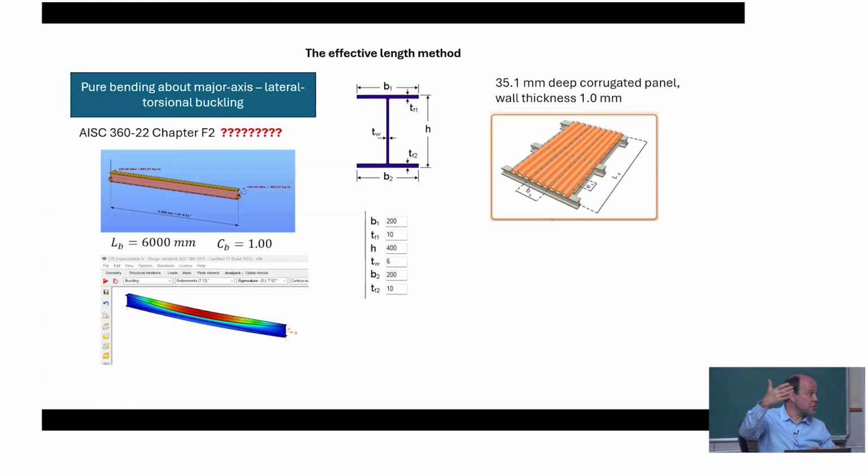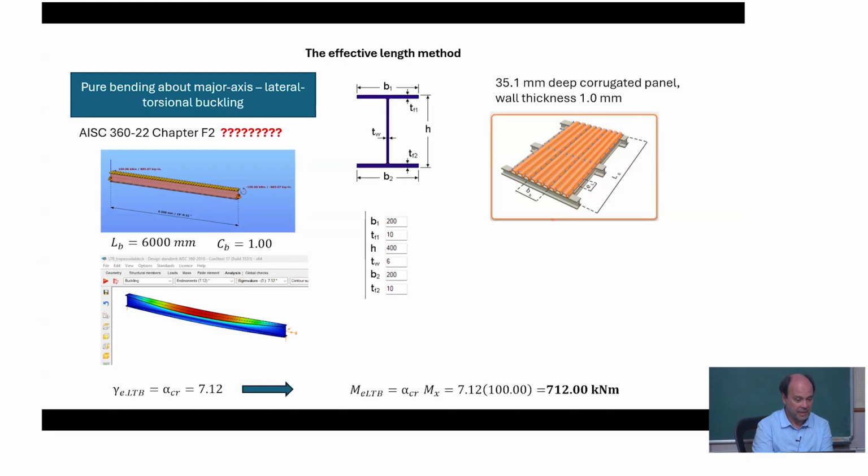It will come under the square root, so you can expect that 6 times bigger will maybe be 2 times smaller slenderness. Depending on what slenderness range we were originally in, we will have a much larger critical stress and smaller slenderness. So for this case, the slenderness will be only 0.9, and that means that we are very close to the cross-section strength, but we are less.